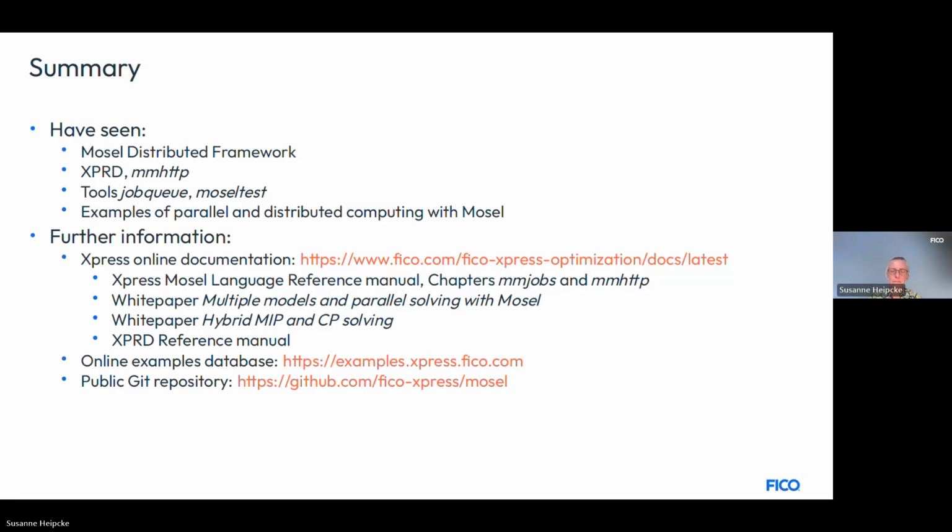Thanks. And then the last part of that question, there are already functions to set an affinity mask. Do you have any recommendations on using them with newer P-core/E-core architectures? Specifically, how to detect which cores in a mask are P versus E when automating across different machines rather than hard coding masks for hardware configuration? Presently we don't provide any specific functionality for this. Also, the Express solver just takes whatever is available in terms of cores. So there is no way of pre-selecting where exactly or which portion of the machine to run this on. The only setting we have for this solver is to limit the number of threads.